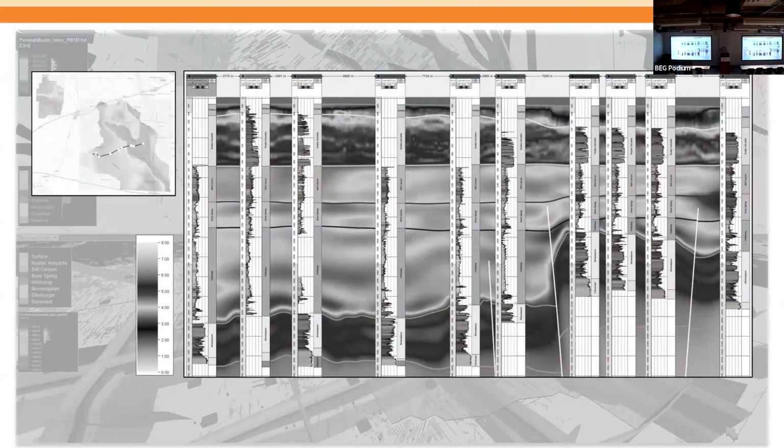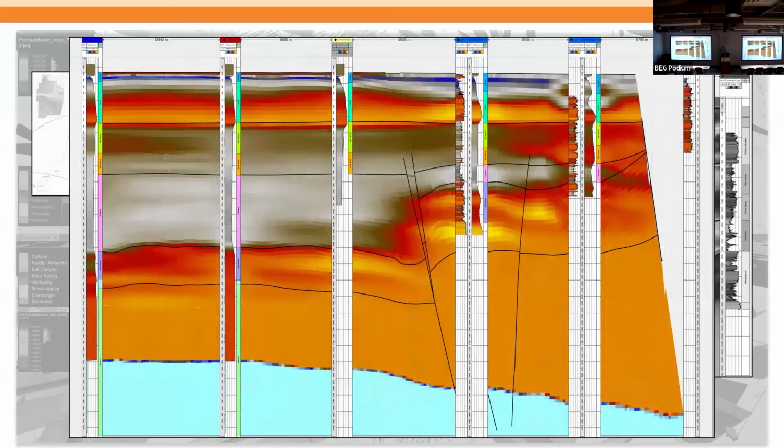Some of the challenges with the velocity distribution, or any sort of petrophysical distribution, in the Permian Basin relate to the fact that you don't incorporate faults. Let me see if I dare to turn on the laser pointer. Right there, that's what happens if you distribute based upon a high-resolution layering framework for the Permian Basin, the actual porosities through the various zones from basement all the way to surface.